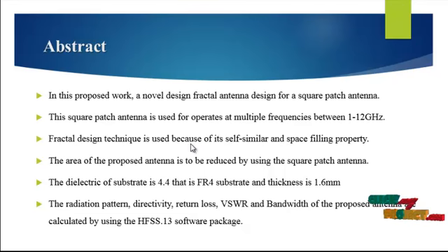The microstrip antenna basically consists of a radiating patch on one side of a dielectric substrate, which has a ground plane on the other side. The patch is generally made of conducting material such as copper or gold, and is very thin. The radiating patches may be square, rectangle, thin strip, circular, elliptical, triangle or any other configuration. The radiating elements and the feed lines are usually photo etched on the dielectric substrate. The microstrip patch antenna is a low profile antenna and has a number of advantages over other antennas.